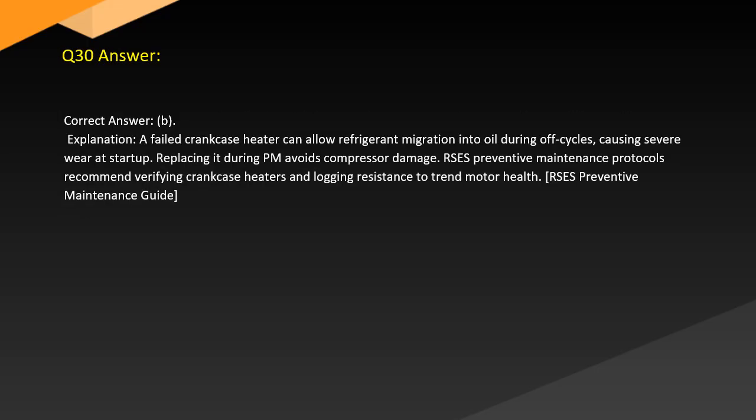Answer. Correct answer: B. Explanation. A failed crankcase heater can allow refrigerant migration into oil during off cycles, causing severe wear at startup. Replacing it during PM avoids compressor damage. RSES preventive maintenance protocols recommend verifying crankcase heaters and logging resistance to trend motor health. RSES preventive maintenance guide.